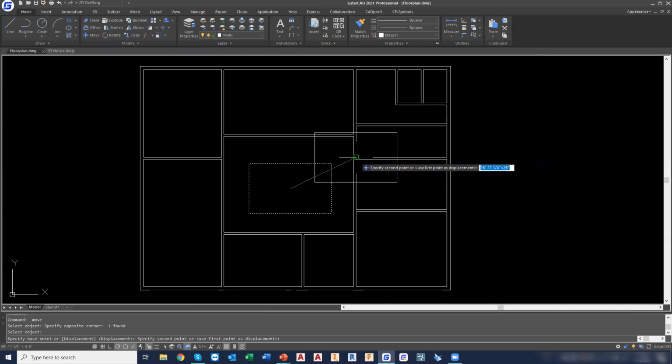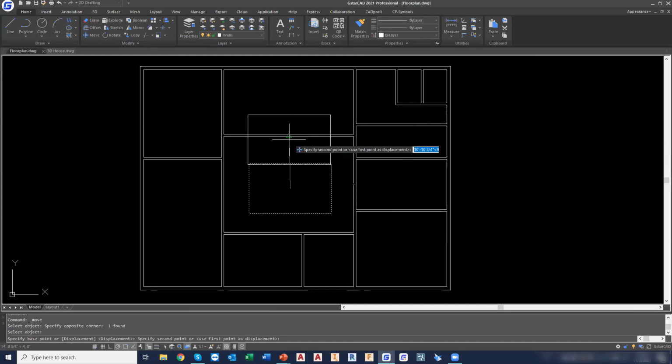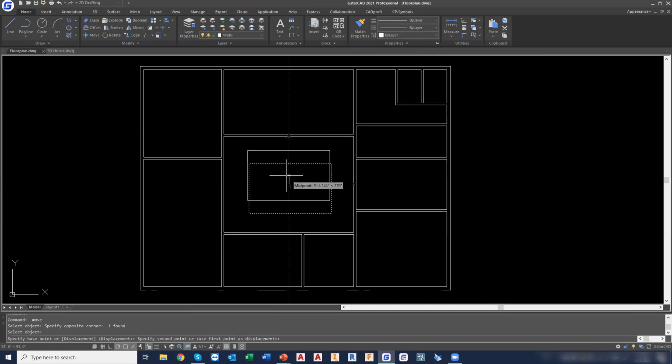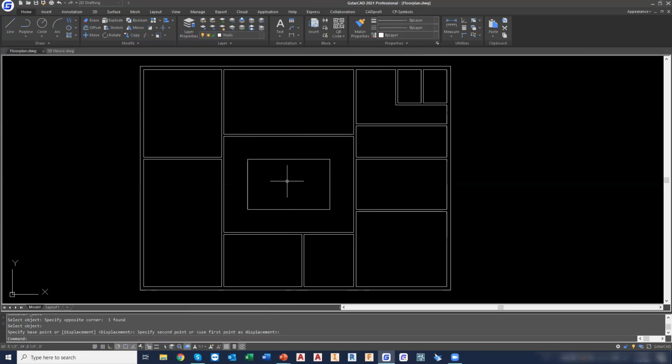Okay, next I'm going to capture the center point of the right line here, center point of the top line, and then move down. And then I'm able to find the center point of that region. And I'm going to click here. And this will make sure that this rectangular region that I'm creating is directly positioned within the area, centralizing its location.